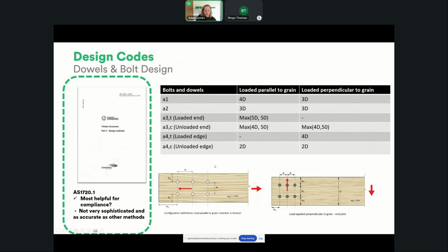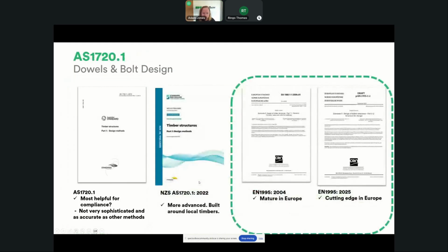And then, of course, on top of that, you've got the edge distance formula, and this is also another fail-safe for splitting of the timber member. If it's too close to the loaded edge, then you're going to have splitting. So there are different checks that you need to do here based on the diameter of the actual fasteners and the relative edge distance. It is slightly different whether it's parallel to the load or perpendicular to the grain.